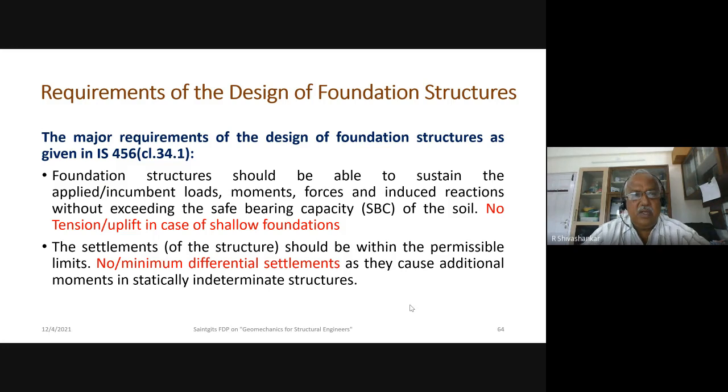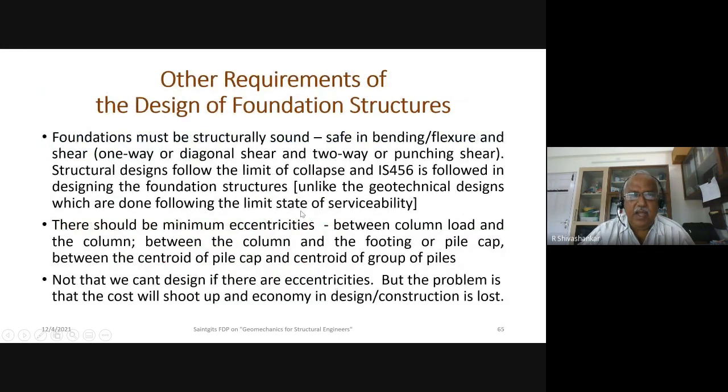Again, the code also says that the load should be safely transferred. In the case of shallow foundations, there should not be any tension, and settlements should be within permissible limits. These two are very, very important, and also the ground should not liquefy, right? And whenever it says that there should be minimum eccentricities and all that, that's not in the hands of the designer. If the client or the owner wants a very unusual structure, we saw so many unusual structures, yes, we should be ready to design that.